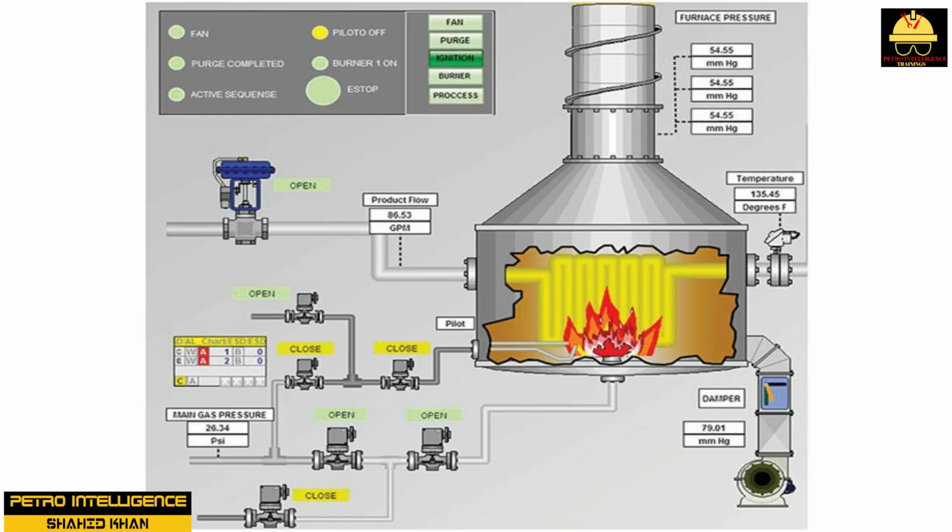Fuel system. Located under or on the side of the furnace is a complex network of lines that provides fuel gas and air to the burners. The fuel is stored in a tank located a safe distance from the furnace. In an oil burning system, atomizing steam and an oil preheating system are added to the network of pipes. Most injuries encountered in furnace operation occur during startup of the fuel burning system.